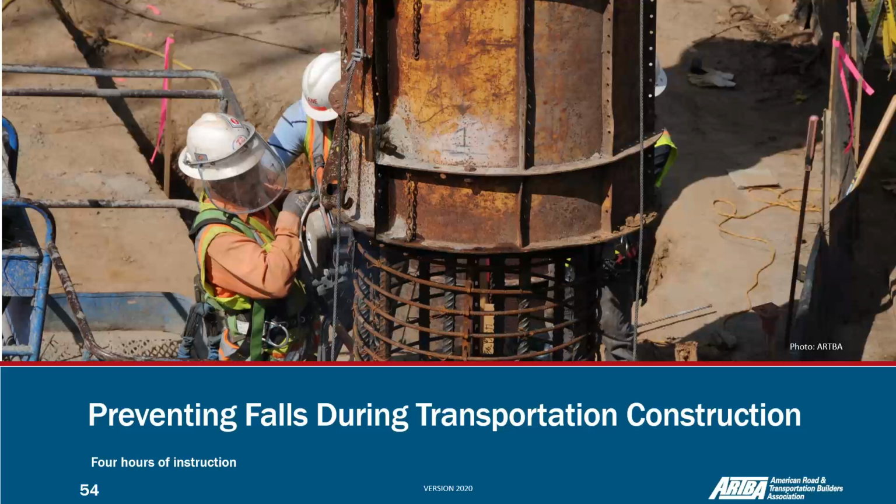We talked a little about warning signs. We can use warning signs on the edge of the fall hazard. The idea is that our workers can work safely inside of this area, preventing them from crossing near the edge, at least 6 feet away.